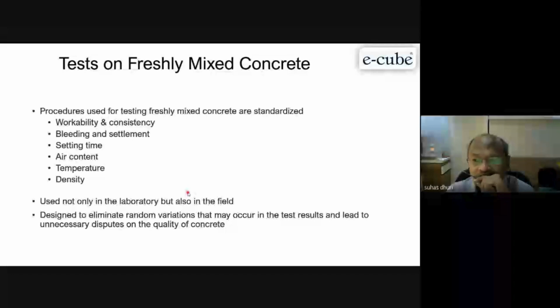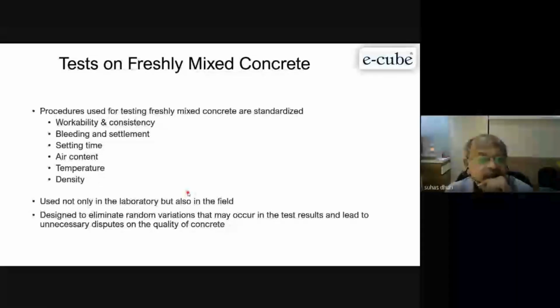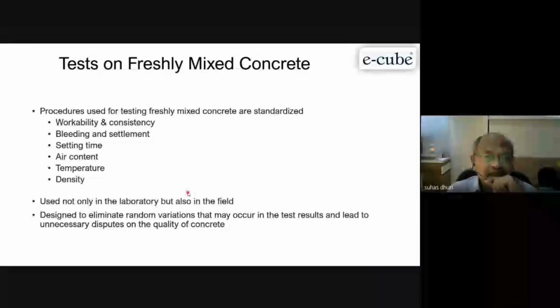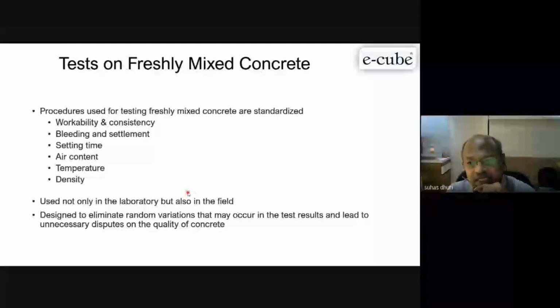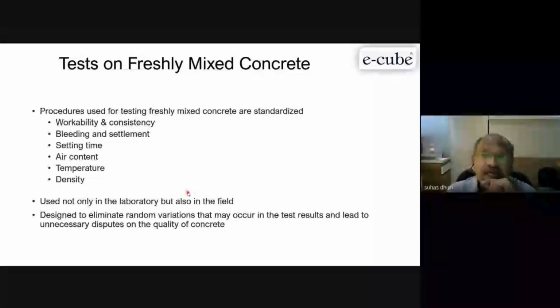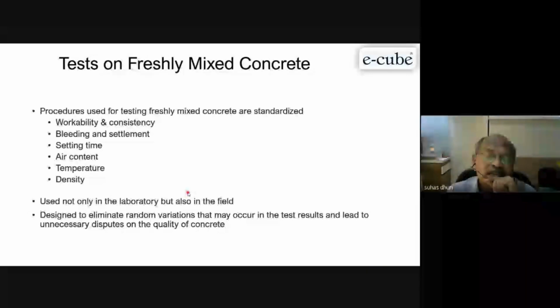So one has to work with a proper cementitious system where my temperature should not go more than 70 degrees at the core of the raft, and my temperature gradient, meaning core to the surface temperature of the concrete, should not be more than 20 degrees. This is the requirement. If this is exceeded, there is a possibility that you may get thermal cracks in the foundation.